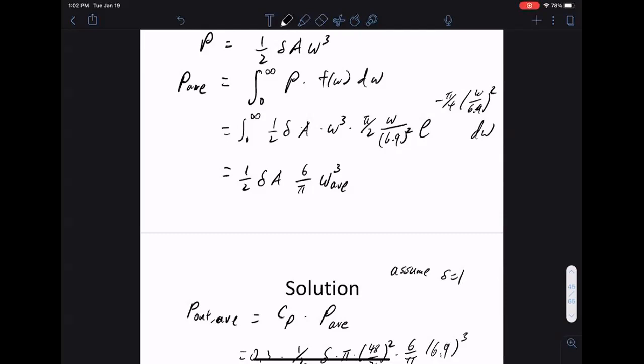One reason we may want this kind of formula is that it gives you a good idea about the sensitivity. With a formula like this, you can easily answer the question: if I increase the wind speed by 5%, how much more power do I get? If I increase the wind speed by 20%, how much power do I get? This kind of formula allows you to answer sensitivity questions. What if I'm off by 10%, what do I get?